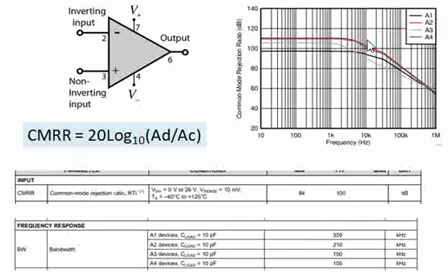As the frequency increases, the CMRR gets reduced. As it gets lowered, that means the common mode gain indirectly is increasing, or the differential gain is getting reduced. We talked about the gain bandwidth product in one of the previous videos. So it might be because the differential gain is getting reduced, meaning CMRR is coming down.